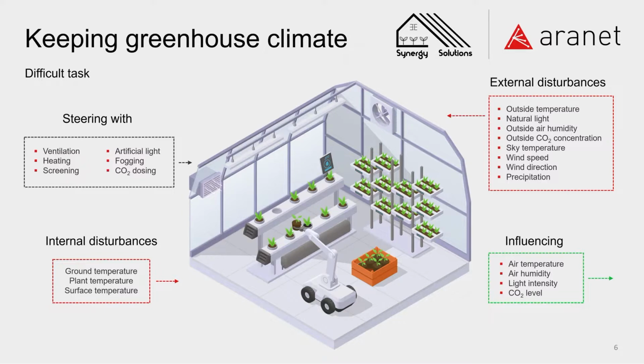and heating as well. So CO2 dosing, also that one, in quite some cases I have seen that CO2 sensors which are measuring the CO2 in the greenhouse, or due to the settings how they are made, are measuring every 4 minutes, and then while the CO2 is dosing you get too high levels, or it is not working at all and just giving some error readings.